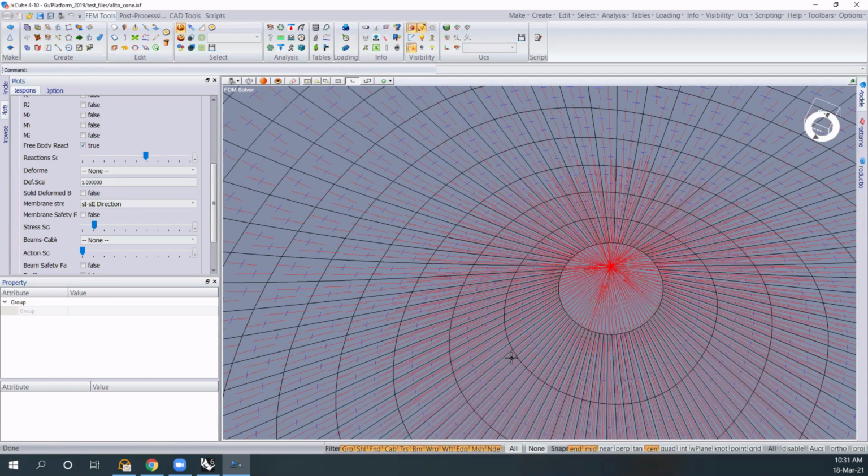Because if we get a membrane and we pull it with a very high stress in one direction, in the opposite direction the stress is very low. You'll see wrinkles in the direction of the high stresses. Is that clear? Try to get a tissue and give a high tension in one direction, and you'll see wrinkles in the direction of the high stresses.